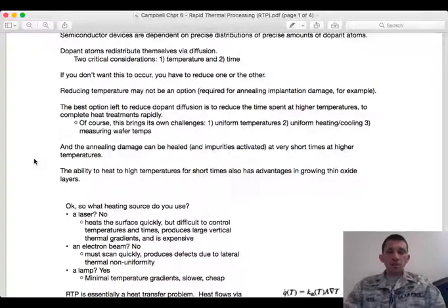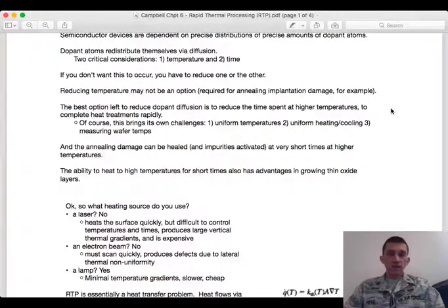And this isn't good. We spent a lot of time making a perfect single crystal, or a high quality single crystal, and so we want those silicon atoms to be on the lattice site. We want the impurity atoms to be on a lattice site, and so we anneal it, right? We raise the temperature high enough that those ions become mobile enough that they can then reestablish that crystalline structure, right? That's the lowest energy arrangement. It's going to naturally, spontaneously get there as long as those atoms are mobile enough.